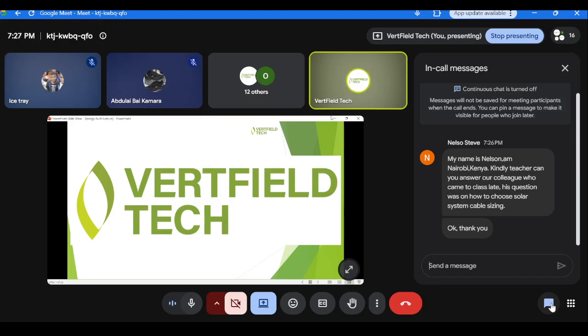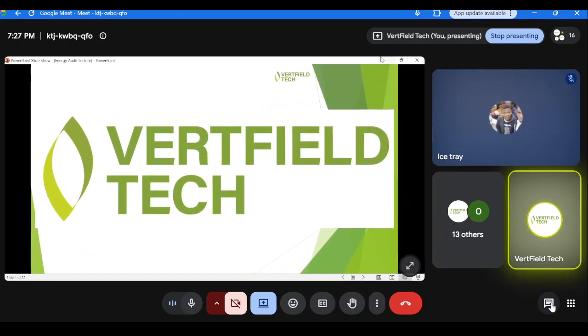All right. So Mr. Nelson, our friend from Kenya, this your question on cable sizing, like we answered it rightly in the last class. We said that this is the basic solar system installation course. Cable sizing has a whole lot of things to do with it. That simply means that it has a high volume, or it is voluminous in nature, such that we cannot just dive into it and finish it up like that. There are so many things to consider: voltage drop, ripples along the line, your system parameters, your IMP, your VMP, your length of transmission is also there.